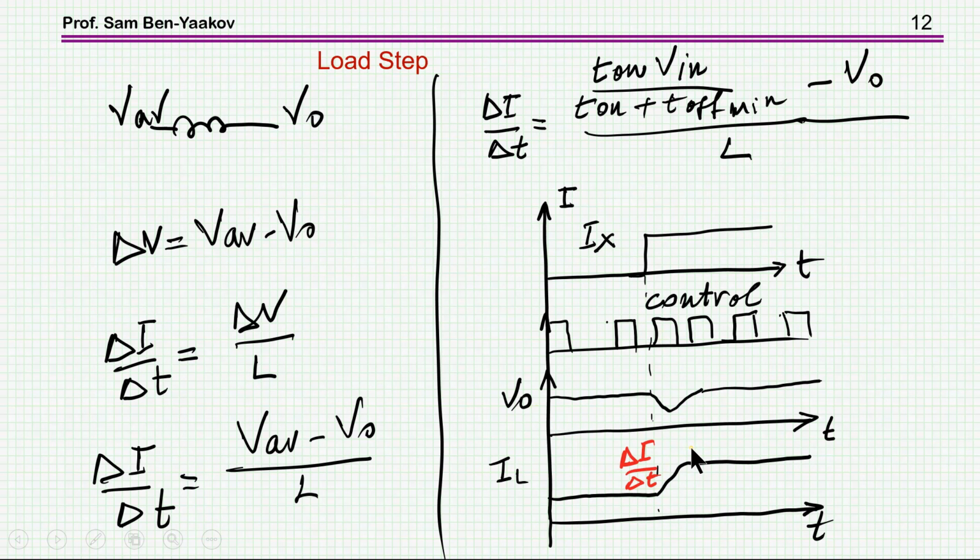Let me just say here, in parentheses, that this is a non-linear control, and the proper way to look at it is in the time domain, because in the frequency domain it really doesn't say much. Injecting AC small signal and looking at the bandwidth really doesn't tell you much about what is happening within the time domain, because it's a highly non-linear system.